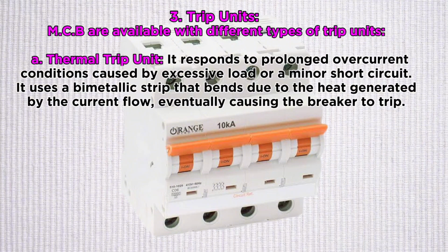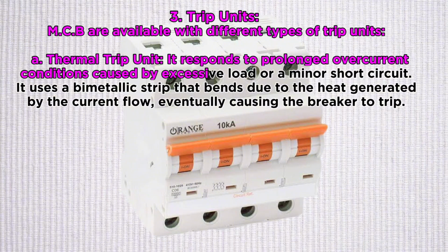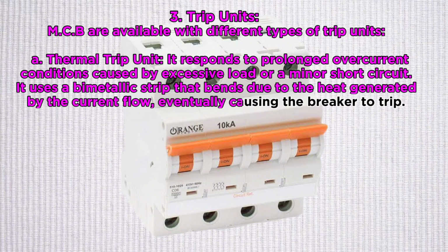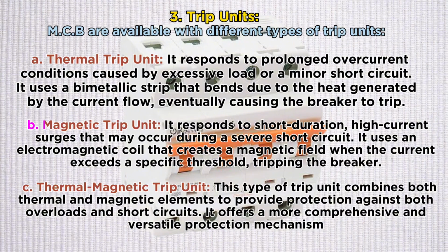A. Thermal trip unit. It responds to prolonged overcurrent conditions caused by excessive load or a minor short circuit. It uses a bimetallic strip that bends due to the heat generated by the current flow, eventually causing the breaker to trip. B. Magnetic trip unit. It responds to short duration, high current surges that may occur during a severe short circuit. It uses an electromagnetic coil that creates a magnetic field when the current exceeds a specific threshold, tripping the breaker.